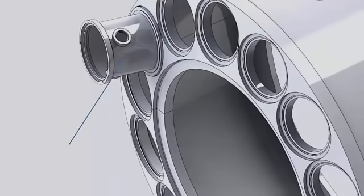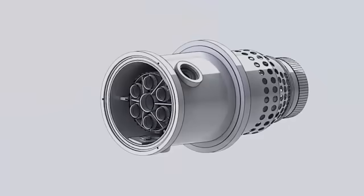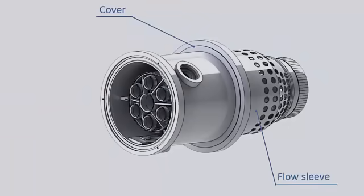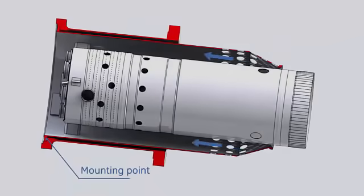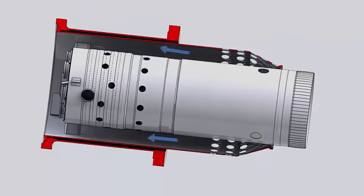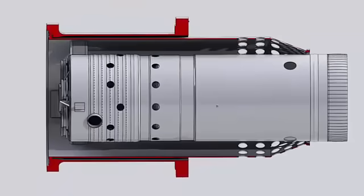The combustion chamber cover function is to carry the combustion chamber components. The flow sleeve is mounted on the combustion chamber cover. The flow sleeve forces the air to move upstream, forming a uniform air jacket around the liner for precise combustion and cooling functions among the 14 chambers. The liner is the core of the combustion system. Inside the liner, air and fuel are mixed and burned, providing hot gases.